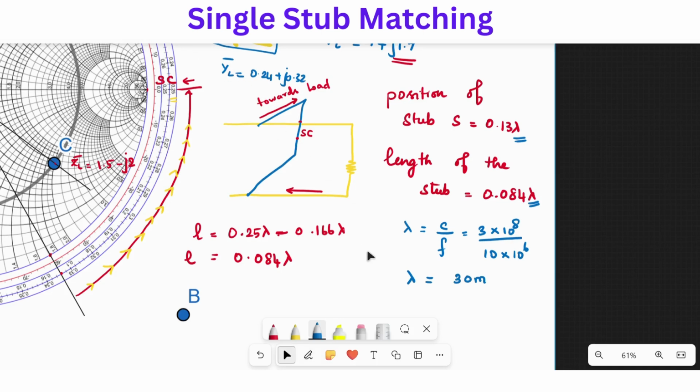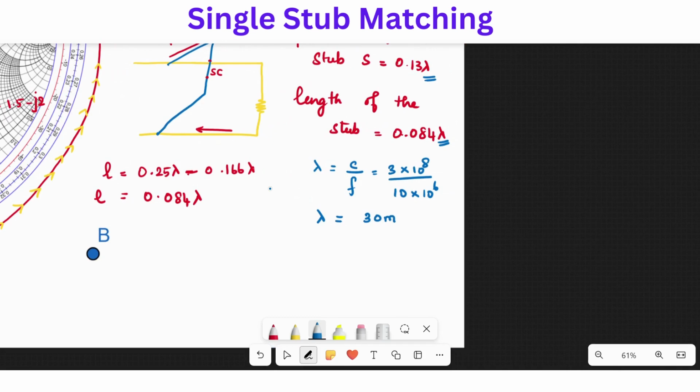So 1 lambda is equal to 30 meters. Therefore, the position of the stub, S, is 0.13 into 30, which gives 3.9 meters, and the length of the stub is 0.084 into 30, which is 2.52 meters. So the problem is over.